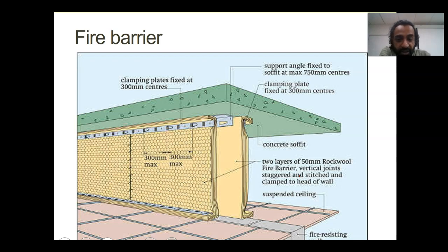And as you can see here, this is where you want to put your layers of barriers, between the rock wall, to protect your insulation and also protect against air transmission from inside to outside.